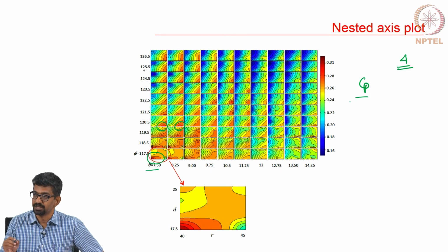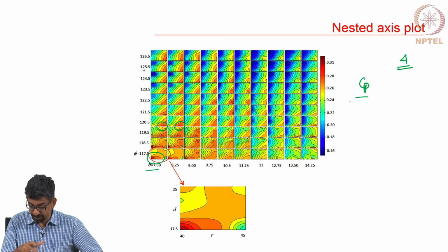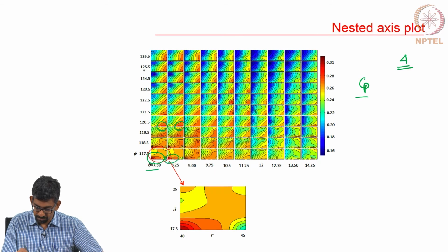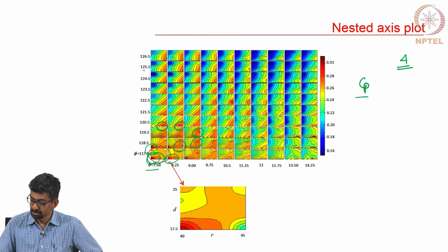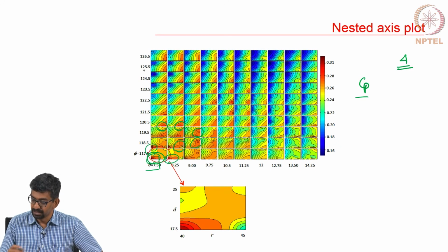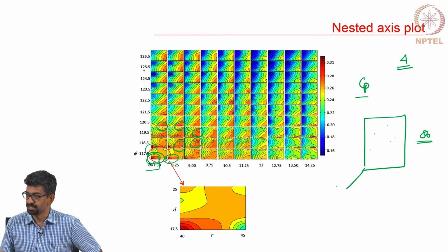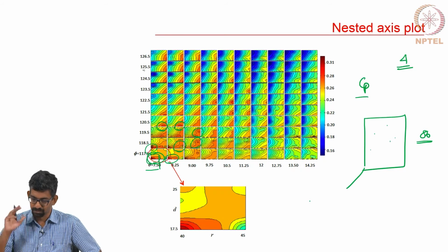We had to perturb a little bit, we have to run computer simulations, that is why we built the computer simulation to begin with. It is expensive, it is still a CFD model, it takes a few hours to run, but we did a few simulations and then we have some zones of interest. This is just based on your nominal value and a little bit of perturbation, it is not the actual fitting. Then what we did is we took the n-dimensional space, which is the 4 dimensional space, and put Latin Hypercube samplings. I think there were about 86 samples, 70 plus 16 samples at the corners, and then we fitted a surface to get the optimal result.